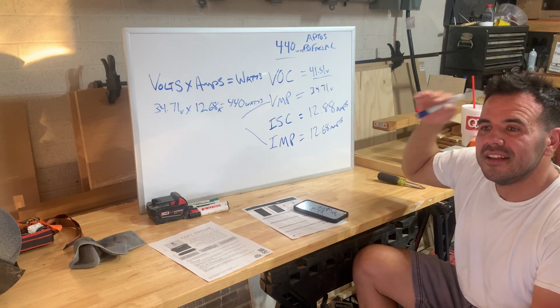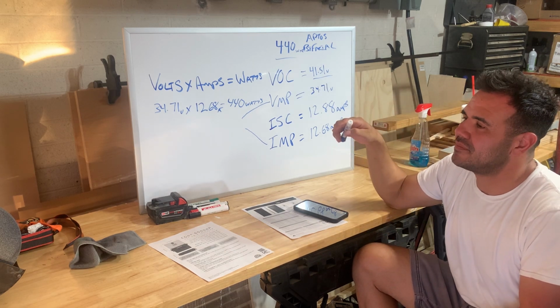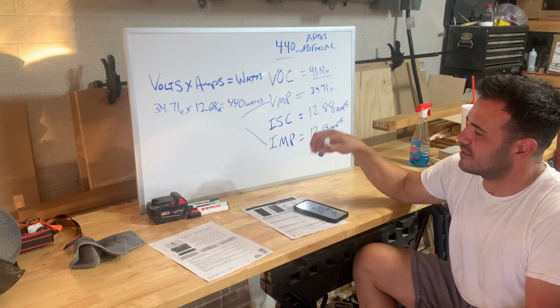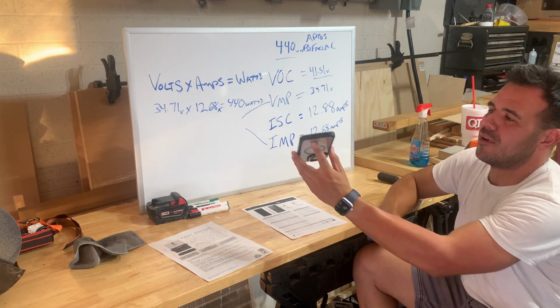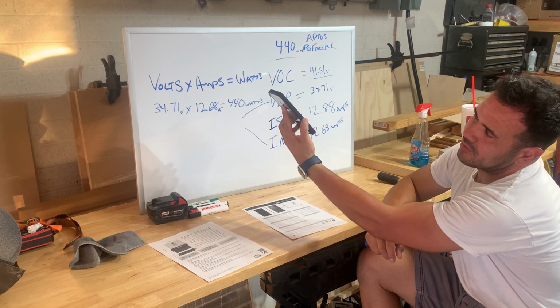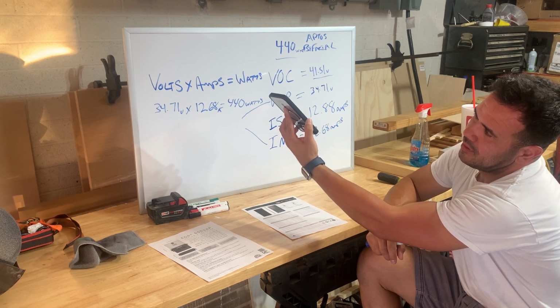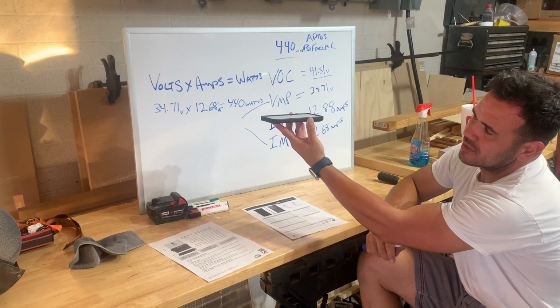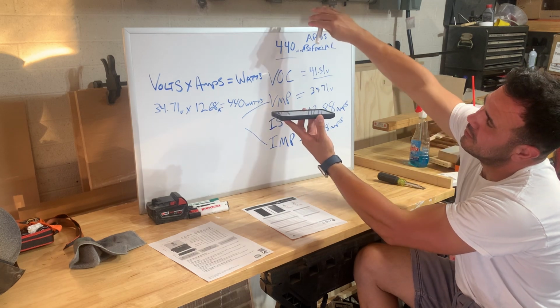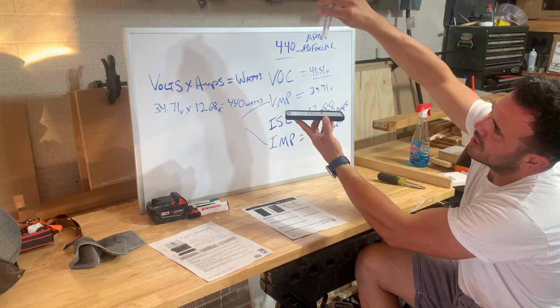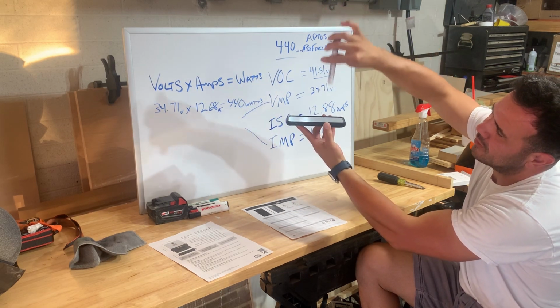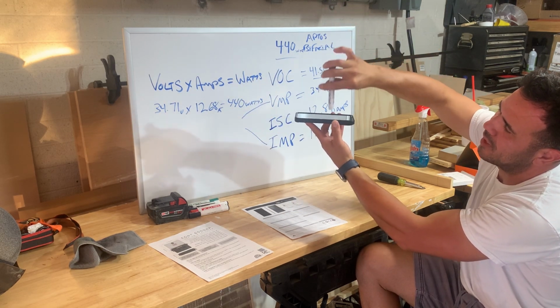So in the summertime, you're going to notice that if your panels are mounted, like my solar panels are mounted on a shed, and the shed is kind of flat. So in the wintertime, I don't really get good efficiency, because the angle that you want is like 45 degrees, maybe more. But my solar panels are just in a fixed position all the time. And so during summertime, they do really well because the sun is almost directly overhead. And it's perfect to give you the perfect angle to hit the solar panels to make power.